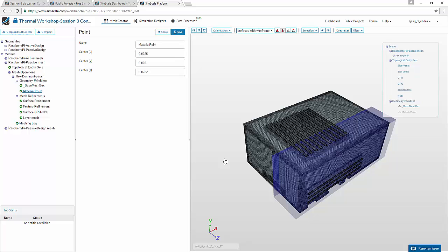So what we do is we create the geometry, create a big bounding box, that is the base mesh box, and keep the material point anywhere outside the car or the aeroplane, so outside the solid body. Now this decides where our mesh should be created. So if you place it outside the car, the mesh would be created in the whole domain except the car, and vice versa. If you place it inside, only the car domain would be meshed.